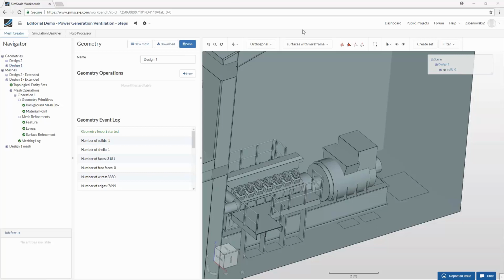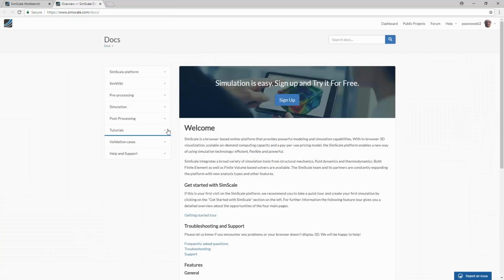I can direct you right now to the documentation at SimScale, because I would have to give you a lecture on approximating thermal flow simulations. So it basically makes your simulations faster, supposing that the temperature difference in your system is low. So you can have only a few degrees of variation in your system, and then it is just calculating it quicker. If you have bigger temperature differences, you should not use the Boussinesq approximation.